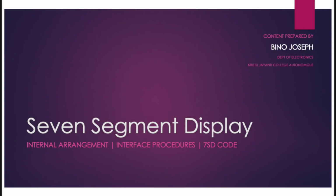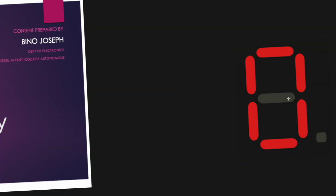The following session will be dealing with a display device called a 7-segment display, which consists of 7 segments and a decimal point. These segments are illuminated from inside with the help of LEDs arranged in the form of an array. The displays can be used for interpreting numbers and a few alphabets, primarily used for hexadecimal displays.